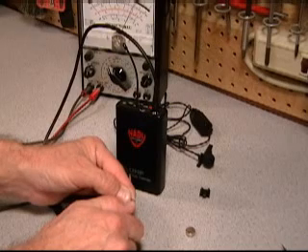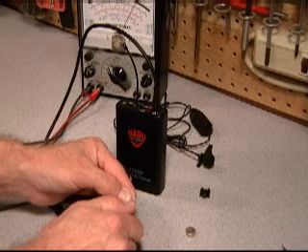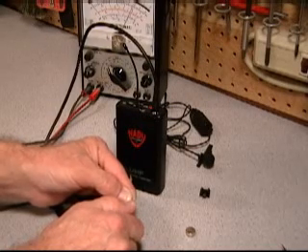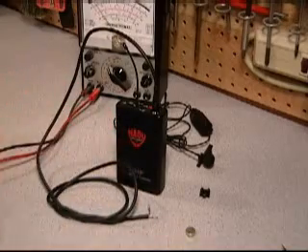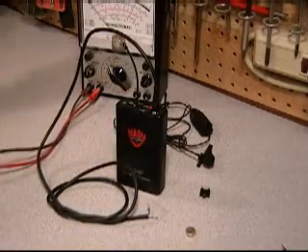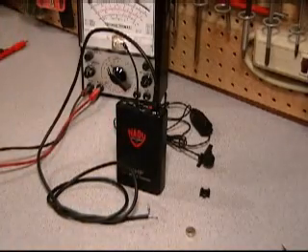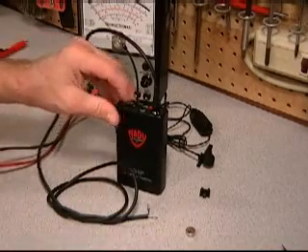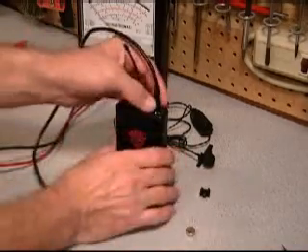So we can eliminate the button cell battery, improve the signal to noise ratio, and improve the dynamic range by switching to phantom power. The problem is that the Radio Shack Lavalier microphone wasn't built for phantom power. However, this is pretty easy to overcome.